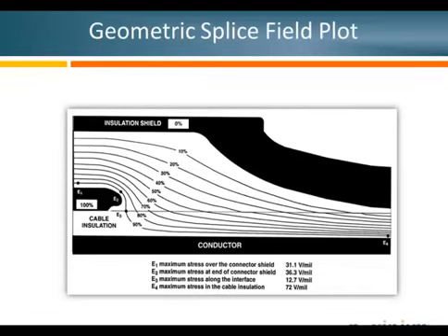So all the air around the connector, there's no potential difference across that, in that air around the connector. So therefore, no potential difference. There's no electrical stress, and therefore you don't ionize that air around the connector.